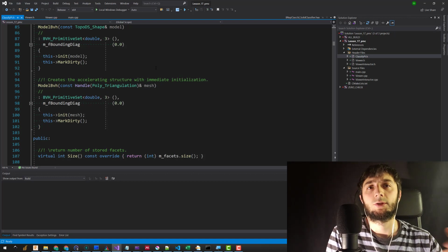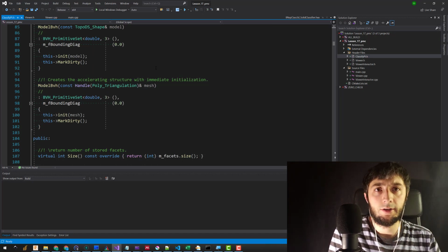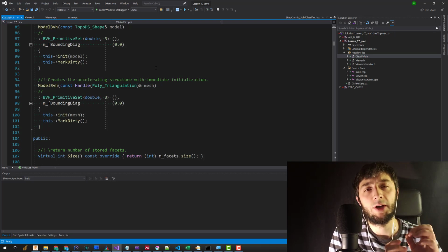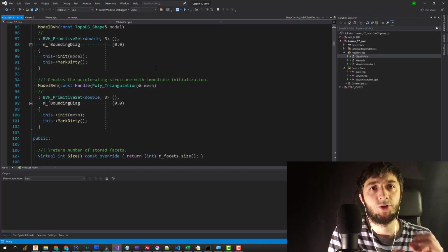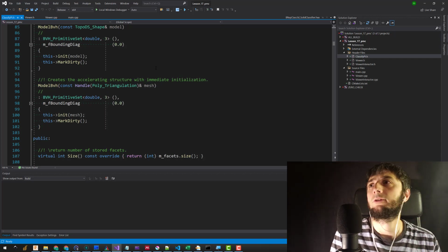Instead of using the boundary representation, or analytical, precise geometry, you first switch to meshes, so you have a faceted representation of your geometry. Then you build a bounding volume hierarchy around it, and then you do very fast filtering. You have a point, you quickly identify which bounding box it belongs to, and then in this bounding box, which is quite small, you do the precise test for triangulation.